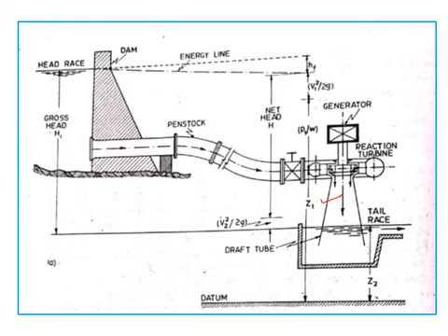So what are the functions of a draft tube? The function of the draft tube is that by having the lower end dipped in the tail race water, a negative pressure head is created at the outlet of the runner or at the inlet of the draft tube, which enables the turbine to be placed above the tail race, so that it will be easy for repairs. And also, by creating a negative head, the net head on the turbine is also increased.